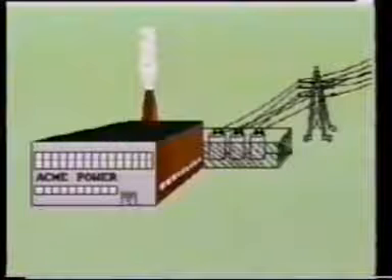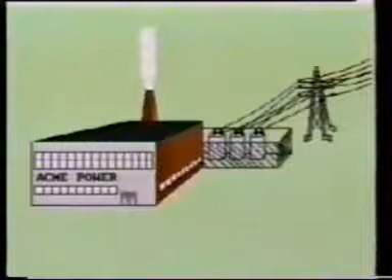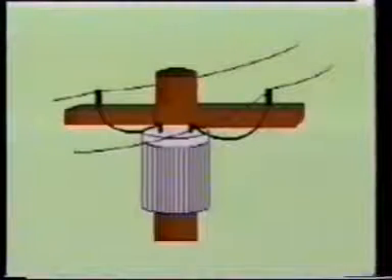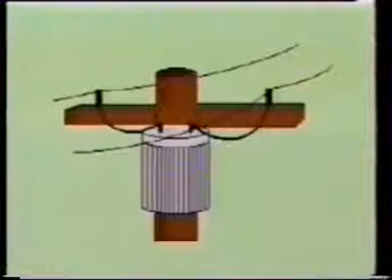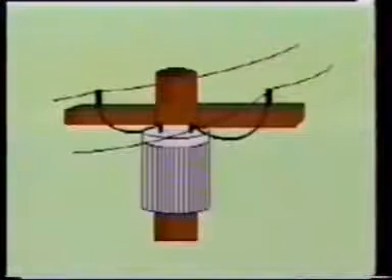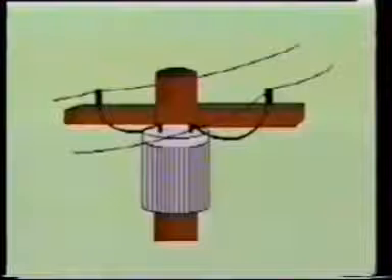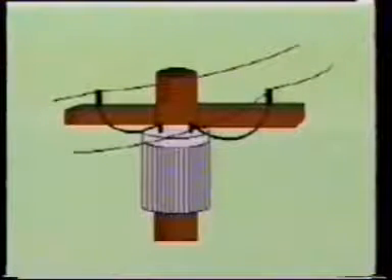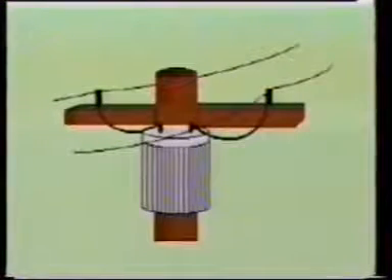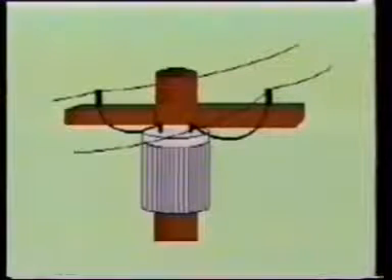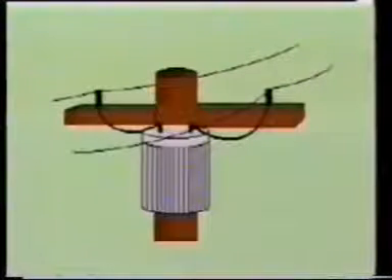be low. Of course, this extremely high voltage cannot be used safely in homes, so it must be lowered to some safer value, usually 120 volts, before it is brought into the homes of the consumers. This task is also performed by transformers. As you will see, transformers can be used to change low-value AC voltages into high-value AC voltages and vice versa, and it is done very efficiently. For this reason, the transformer costs very little to operate.